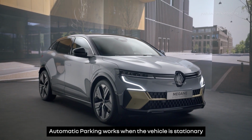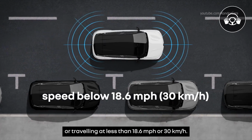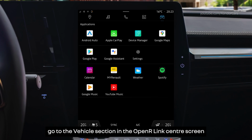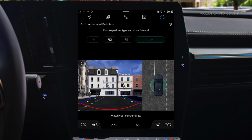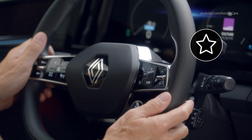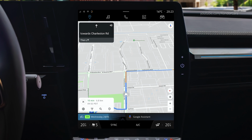Automatic parking works when the vehicle is stationary or traveling at less than 18.6 miles per hour or 30 kilometers per hour. To turn this feature on, go to the Vehicle section in the Open R-Link center screen and select Automatic Parking. Depending on your personal settings, you can also turn this feature on with the Favorites button on the steering wheel, or by selecting the Automatic Parking widget on the home screen of the multimedia system.